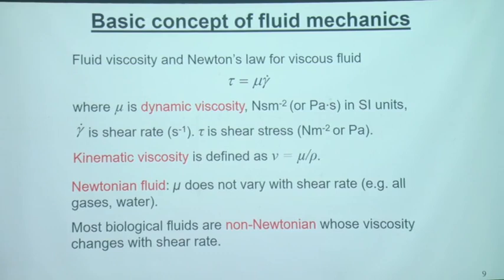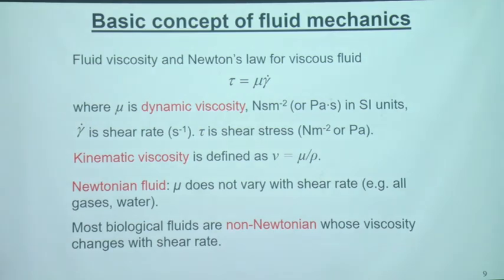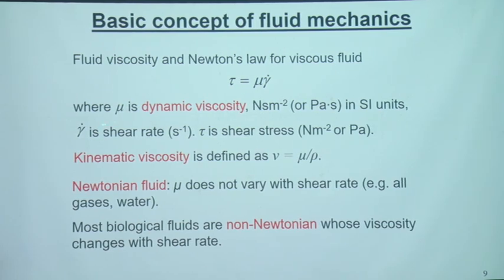Now we can move on to look at some fluid mechanics quantities, for example, fluid viscosity and Newton's law for viscous fluid. Here we define shear stress. Shear stress is the product of dynamic viscosity and the shear rate. Here mu is the dynamic viscosity. For a Newtonian fluid, the viscosity is constant.